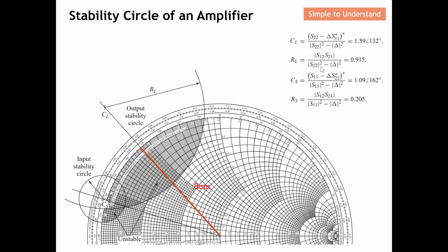And when this is 1.59, what I need to do is plot 1.59 multiplied by the reference point, which is 8 centimeter. As I told you earlier, we do a measurement and indicate this as a reference, which is 8 centimeter. So what we plot on the center of the loop is 1.59 multiplied by 8. Therefore I need to plot at 12.72 centimeter away. So this length needs to be 12.72 centimeter, and I indicate it over here. I hope it's clear.